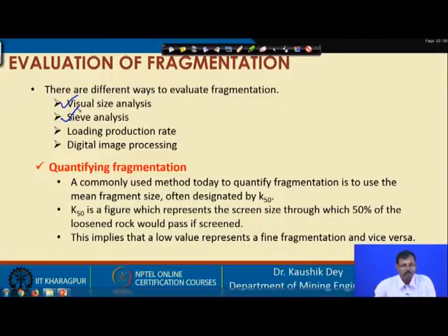So, this is very important, and this basically gives us the most accurate, the best method of analyzing the fragmentation. However, the problem is that when we have bigger boulders like 1 meter cube or 1.5 meter cube, placing those boulders on a sieve needs a big sieve, and then mechanical power is required to shake that sieve.